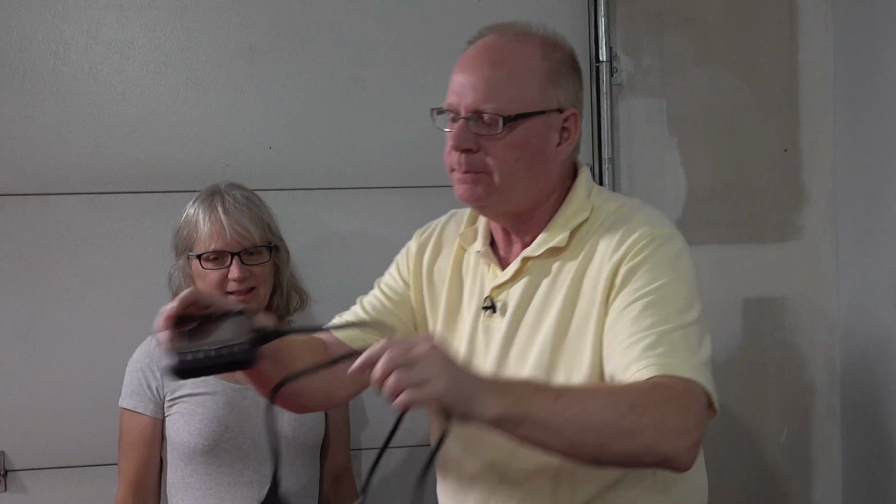Right. Well, we were going to return this reader because it wouldn't work. And then I was doing some research trying to figure out what to do next. And I noticed that this reader just flat out wouldn't read anything when I set it up for this car. But when I set it up for a model that was 3 years later, it actually read the engine control module, just wouldn't read the transmission control module.